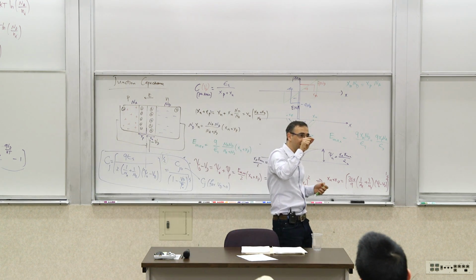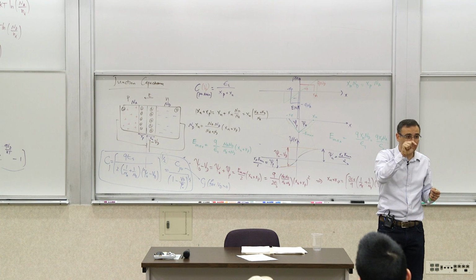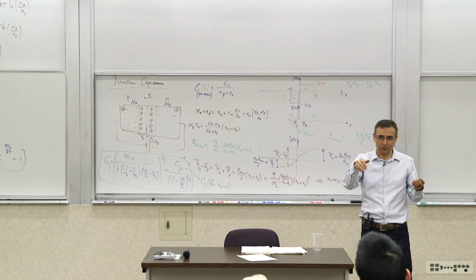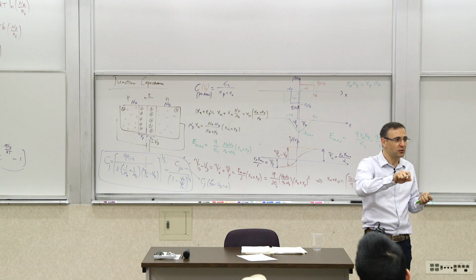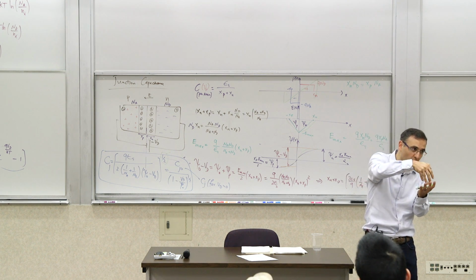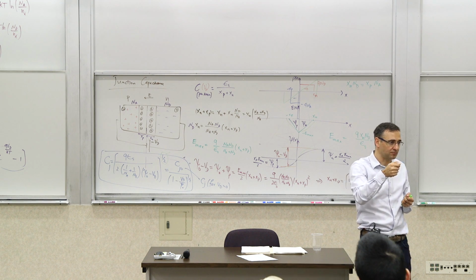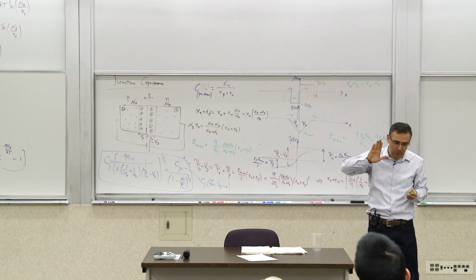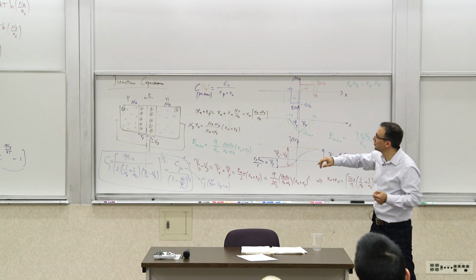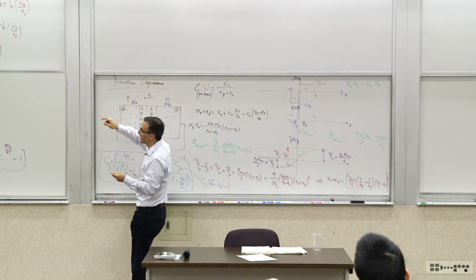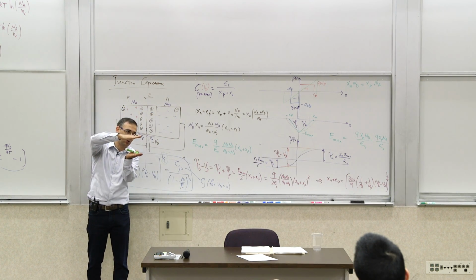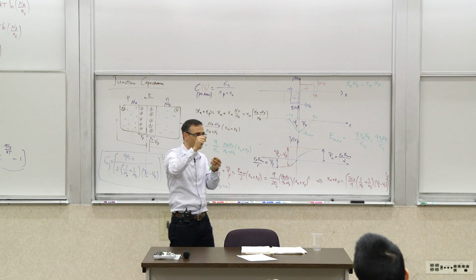So these carriers now start, due to their thermal energy, to move in there. Or in other words, diffuse, or diffusion. Due to diffusion, they would just diffuse and go inside. And by controlling the temperature and the time you had that going on, they would form a certain profile. And then you introduce a second layer, which was the opposite, and they would go in and settle at a lower depth, and they would form a junction. So that was the old days.